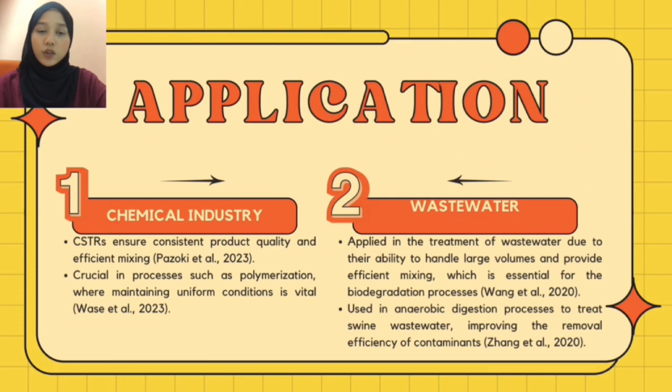The article describes using a genetic algorithm to modify the PID controller settings to minimize absolute error and regulate input changes. Fuzzy gain scheduling using the Takagi-Sugeno model interpolates local controller output in different operating zones. This guarantees accurate temperature management and enhances control system disturbance rejection. This new method outperforms classic PID controllers, making it a promising option for chemical industry CSTR regulation.